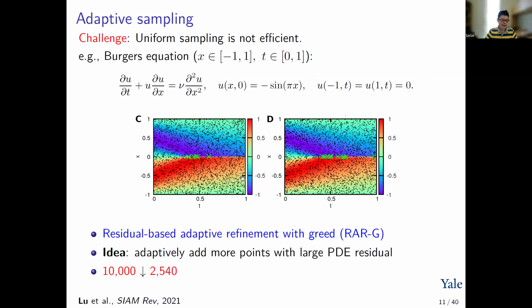So usually when we do finite difference or finite element, we would apply a mesh refinement and draw a denser mesh around this location. We can apply this idea also to PINNs. So we can start with a random sampling of locations, as shown in the black dots here. Then we do the training for some iterations.